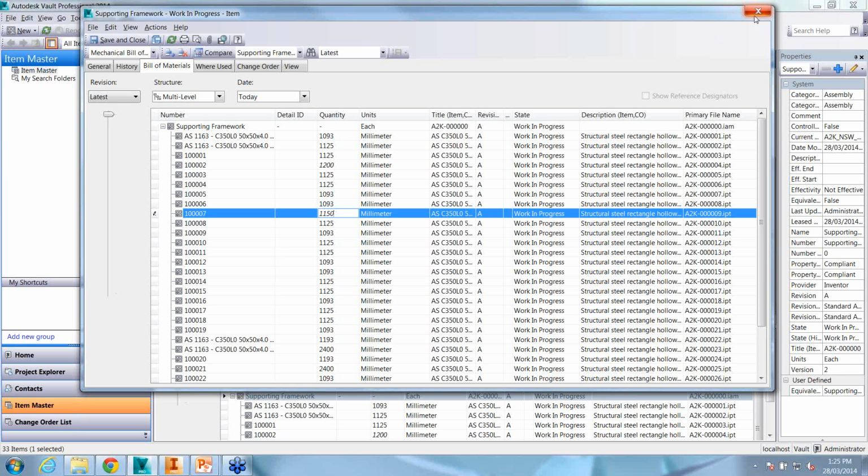The other way would be using Inventor and iLogic. So you could use a custom property, and you could call it actual length plus runout. And you could use iLogic or even just the equation editor inside the parameter table. You could always say that your parameter, which is your length plus runout, is always equal to the parameter, which is actual length, multiplied by 1.1.